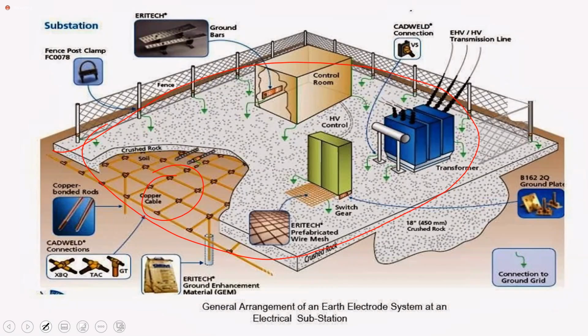I want you to note that here we have the switchgear, so that would be your breaker. Note you have a mat. When you're working on any piece of equipment within the substation, there will be a little metal mat that you need to stand on. That's for your own protection, even though you have on safety boots. And that is the switchgear. You see the little green thing there? That's showing you that it is connected to earth. Your transformer is connected to earth.